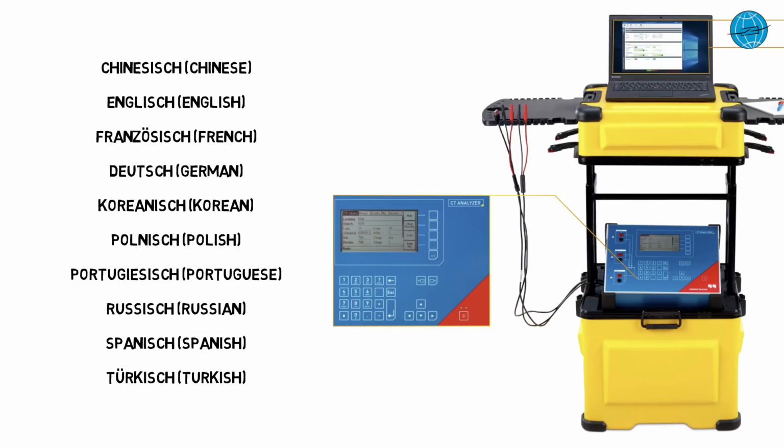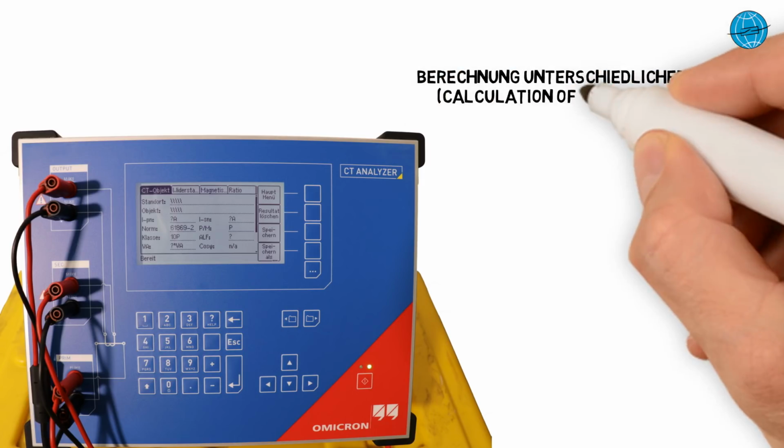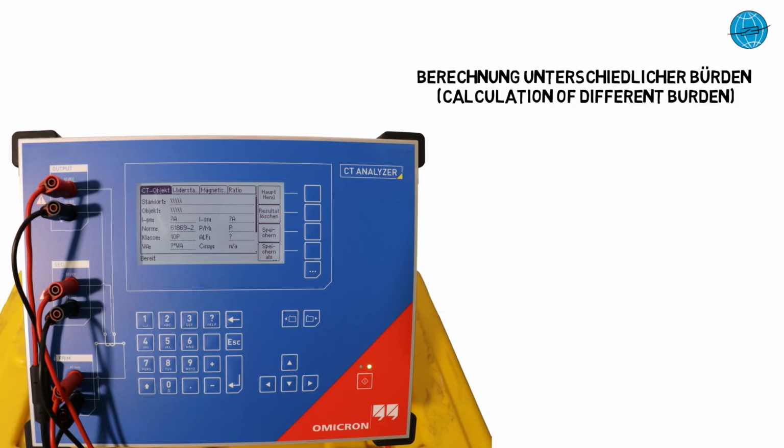An ingenious function of the CT Analyzer is the possibility to simulate different burdens. Whenever a change in burden affects the accuracy of the measured CT, the CT Analyzer can easily calculate the results for different loads and primary currents after a single measurement.